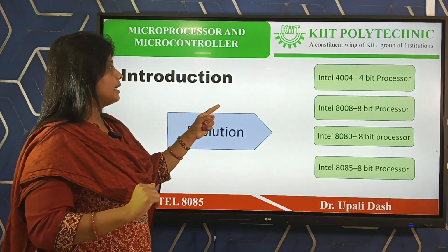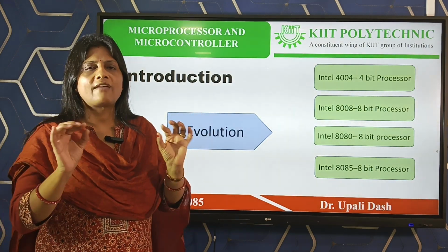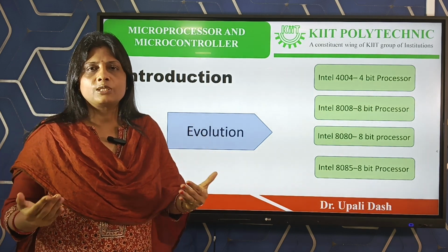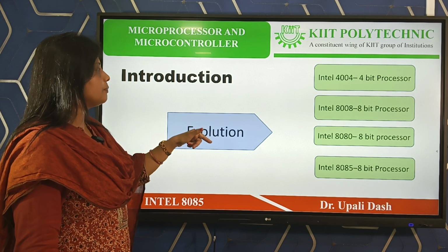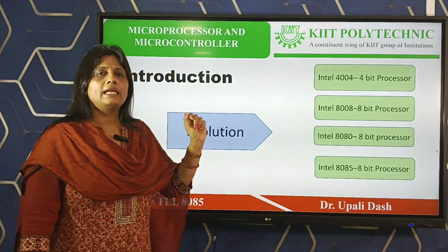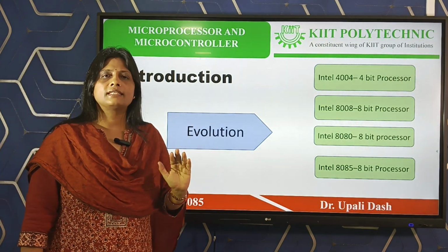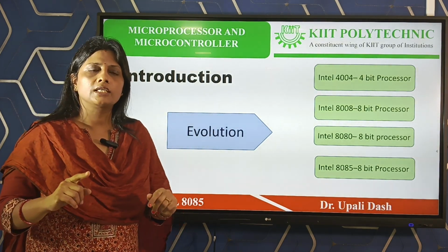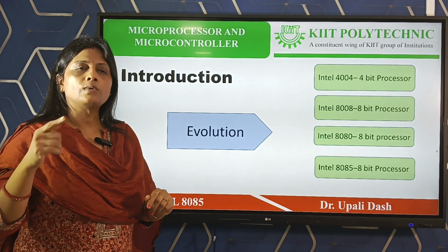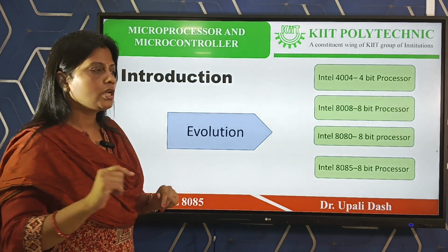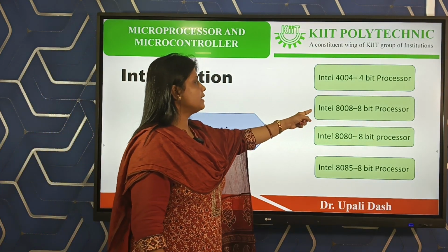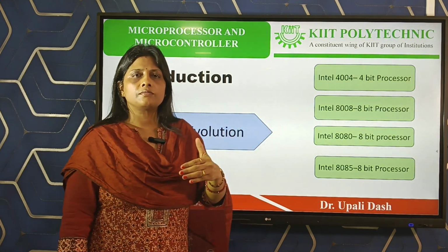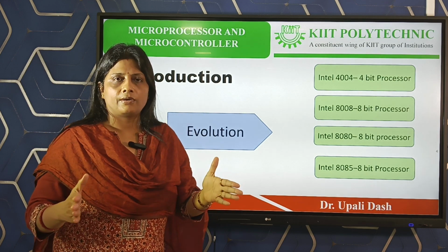Intel 8008 was a successful processor, but with this limitation of mobility and lower speed. So we got another 8-bit processor in the year 1973 itself, Intel 8080. The plus point was that it was using NMOS technology, so Intel 8080 is improved over the earlier technology in terms of data speed.